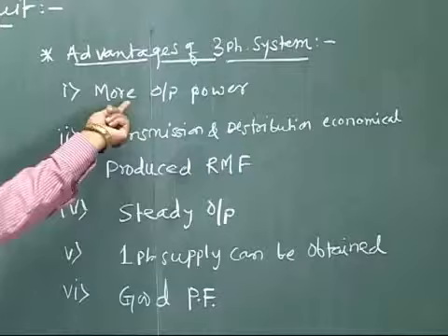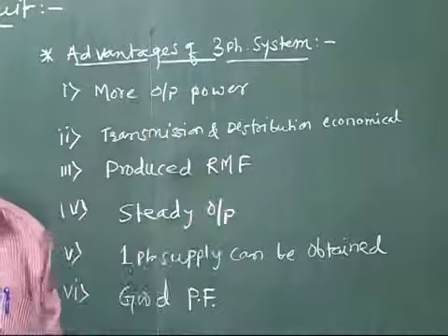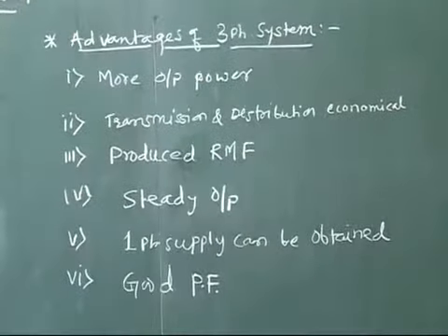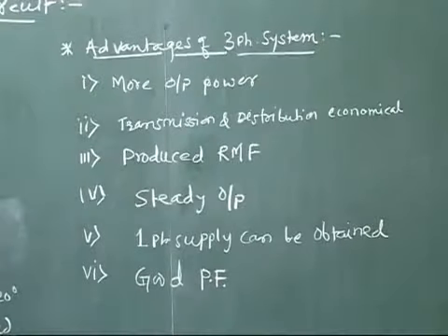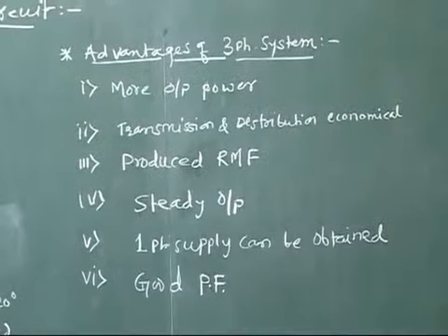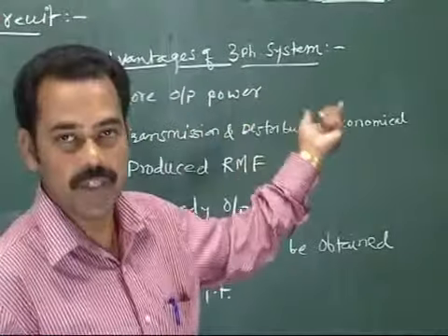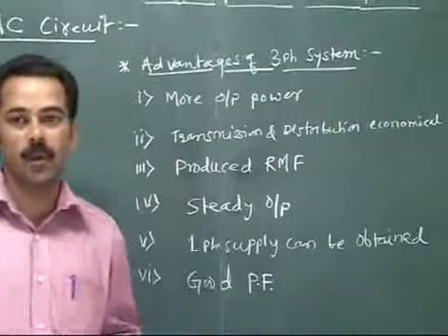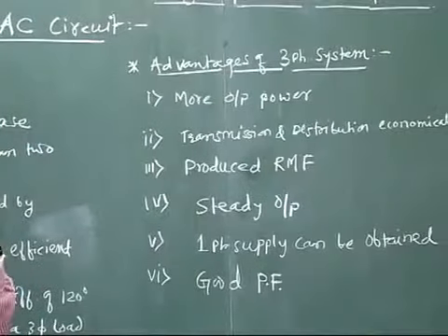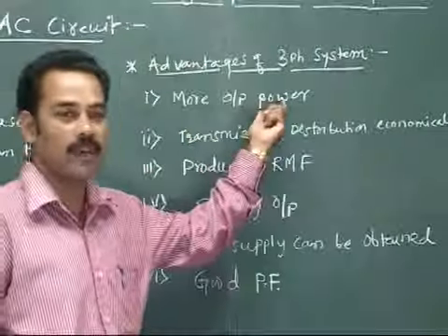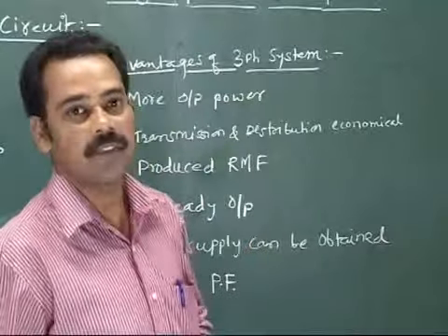The first advantage is more output power. For the same size of motor or alternator, if you take a three-phase as well as a single-phase machine, the output power of the three-phase machine is always greater than the single-phase machine, approximately 1.5 times the single-phase power.